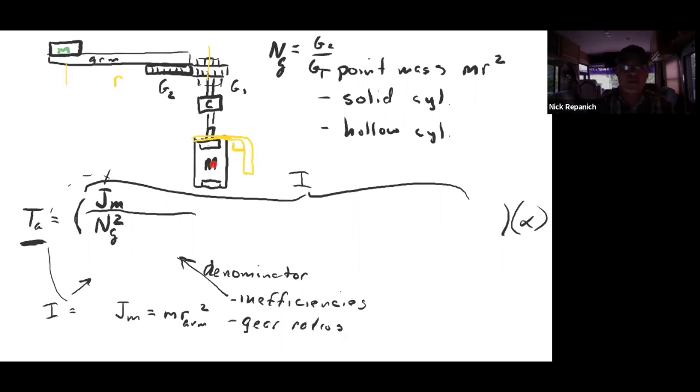You probably didn't get that proven out to you, but if you just say power in is power out and work through torque times speed and torque times speed, pretty soon you'll get to the speed of this gear and the speed of that gear is the gear ratio, and you'll get to, oh, it's the gear ratio squared. So you can derive that, not too difficult. Gear ratio squared. Okay, so now we're on that gear.